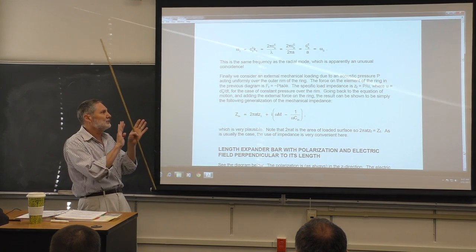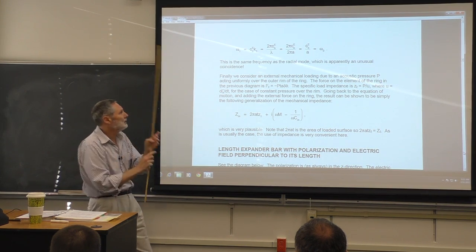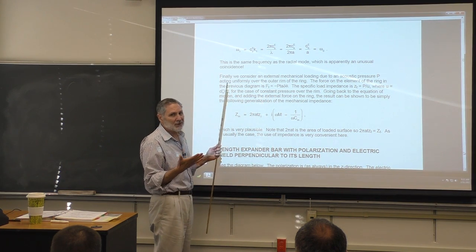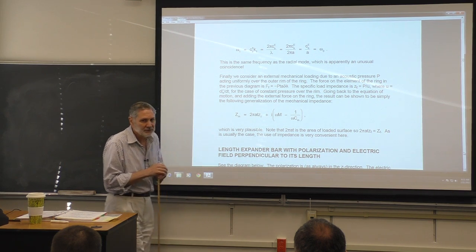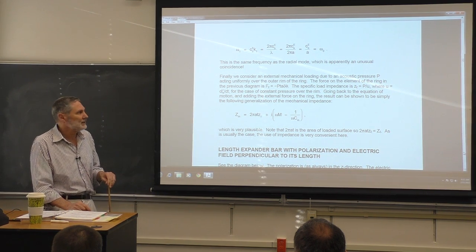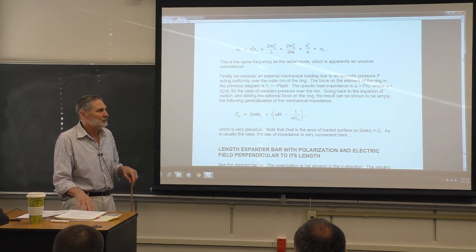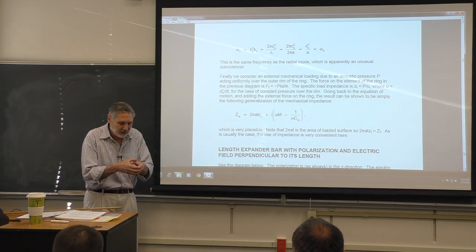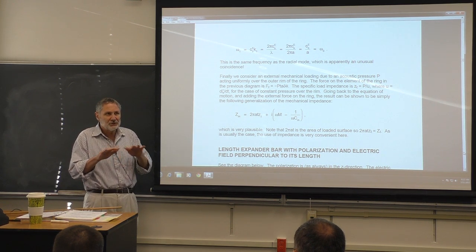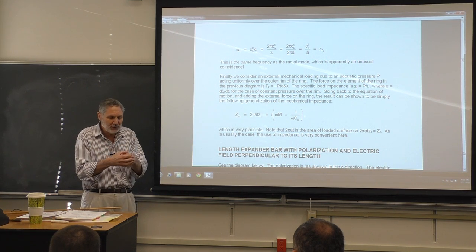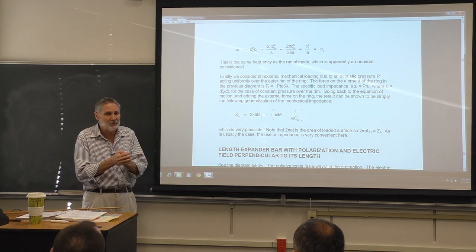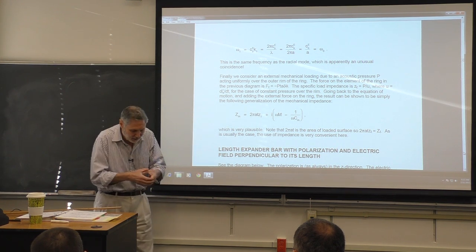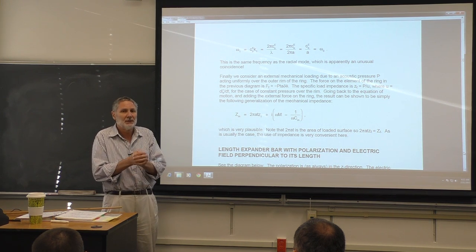We're going to assume that it's restricted to that outer edge, okay? There'll be a load force now, and we'll assume it's a uniform pressure, which is the typical case. I haven't emphasized that in this class, but we'll start to see it more and more. The typical case here is an element. You may have a sonar projector that's composed of a lot of elements, but if you look at each element, the wavelength is almost always large compared to the element. That's really convenient theoretically, because what that means is the pressure will be the same here.